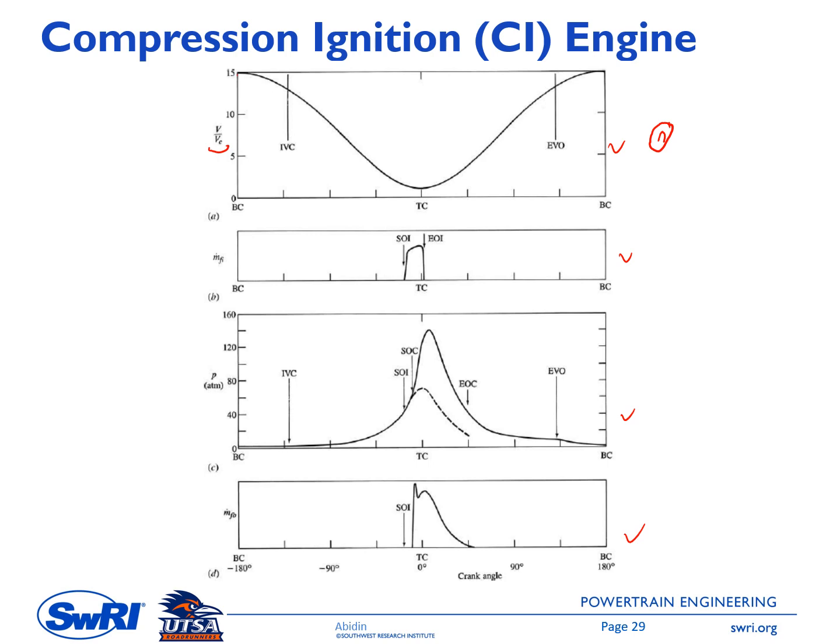So we have a 15 here when the piston is at BDC. And then we have IVC at this point, and then you will have a compression process, and then the volume will be minimum when the piston is at TDC, and then it will be maximum again as the piston moves down toward bottom center, and we have the exhaust valve opening here.